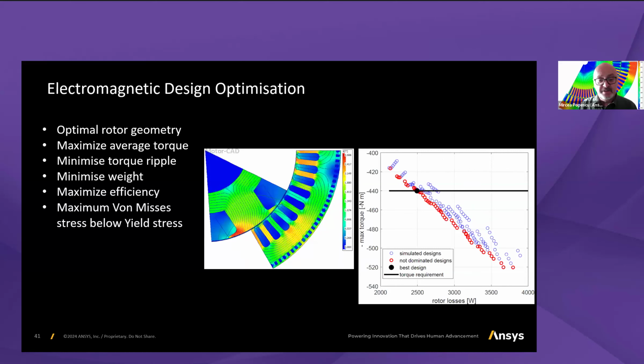And this is what we managed to achieve through optimization. The target was easier because the stator is already fixed. We had only to vary the number of turns per coil for the stator. You notice these channels on the stator lamination through which the liquid is circulated to cool the stator assembly.